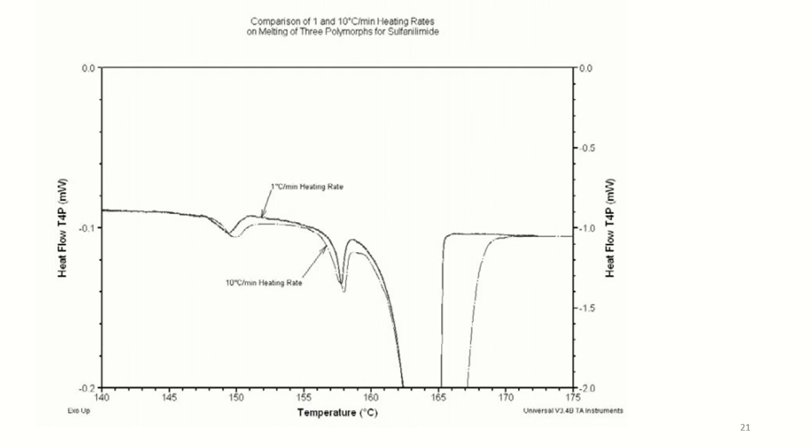Note that heating rate has very little effect on the number and shape of the melting peaks, except for slight broadening of the large peak near 165 degrees Celsius. This means that each polymorphic form is relatively stable and does not transform from one form to another during that particular experiment.